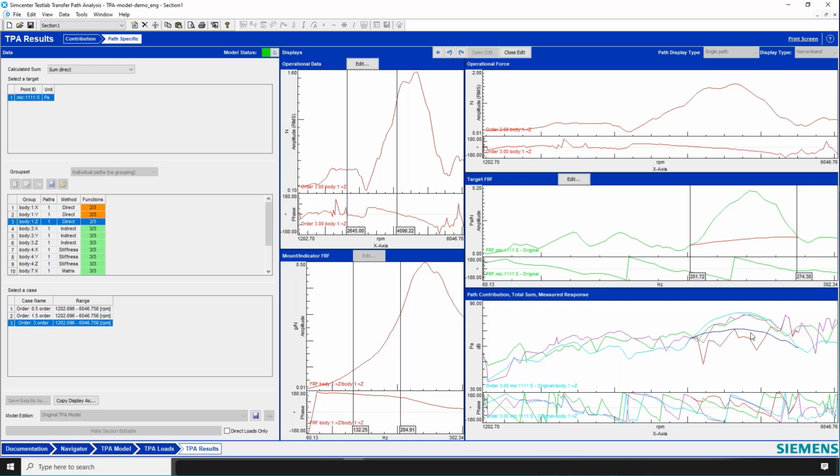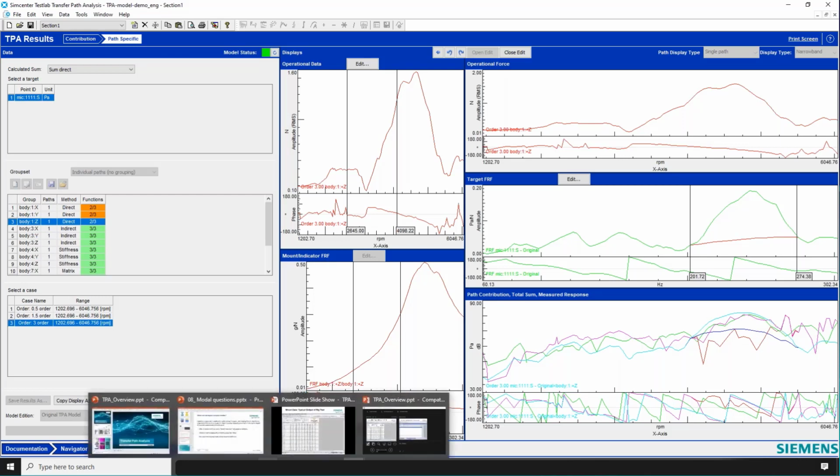So it lets you actually, once you've organized this data with the FRFs of the structure and the source data, you can do these kind of what if games and get some insight into what's going on. You have a path with mounts, you can identify mount resonances and things like that as well.